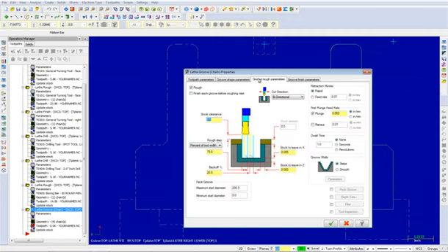Enable the option to rough the groove and disable the option to finish each groove before roughing next. Also, set the cut direction to positive. Ensure that you set retraction moves to rapid and a back-off percentage of 20. Then choose the Groove Finish Parameters tab and input an overlap between passes value of 0.01.